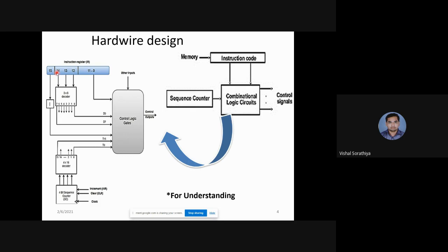But now if you say that you want to do XORing, we can say the XOR instruction is not directly available in this hardware design. Why? Because the control signals generated by that control logic block are fixed for the instructions related to add, AND, and OR. If you want XOR, you need to write a program for that, and under that program your AND, OR, or NOT gates are going to be included.